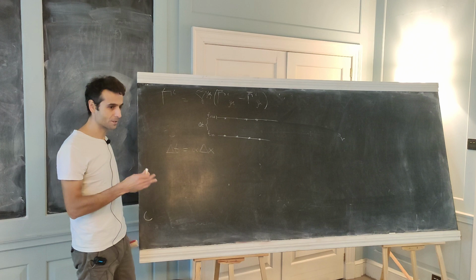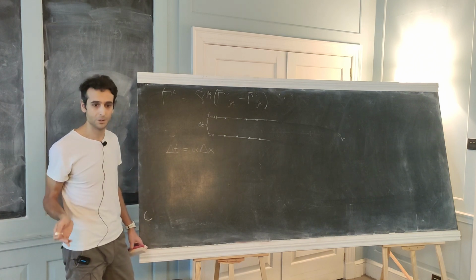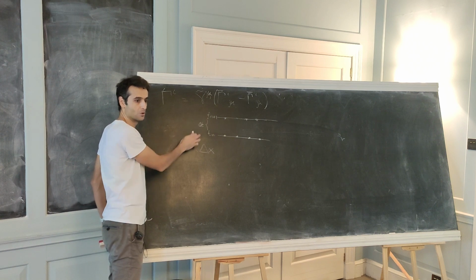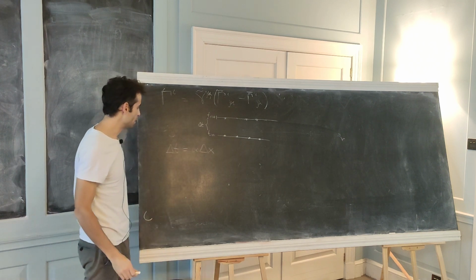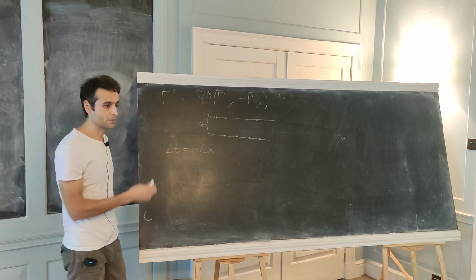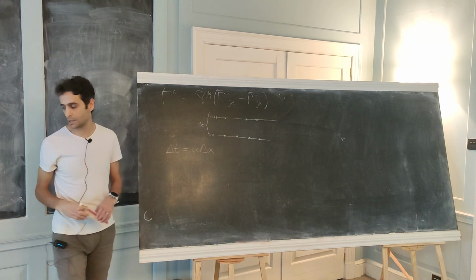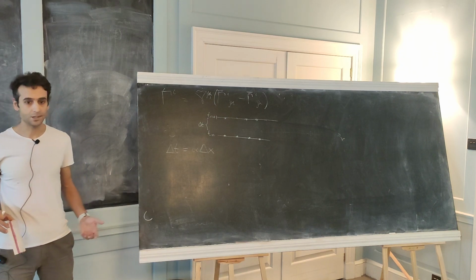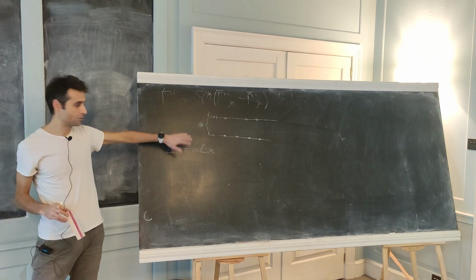If it's too large, the code is not going to converge, because the level will not be causally connected to this. Here we choose it to be 0.25, which is pretty standard, because we use an explicit time stepping, like Runge-Kutta 4, which is a standard. But if you use an implicit scheme, then you don't need to worry about this.